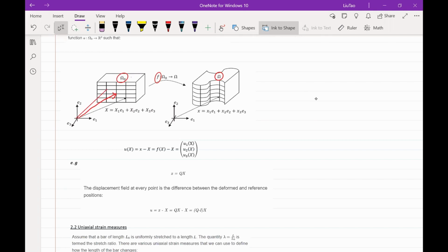First, we assume that deformation between configurations preserves the distinction between material points, which restricts f to be bijective. It means all points in the undeformed space are also in the deformed space, and vice versa. Second, we assume that material points do not change their adjacent points. This restricts f to be continuous.